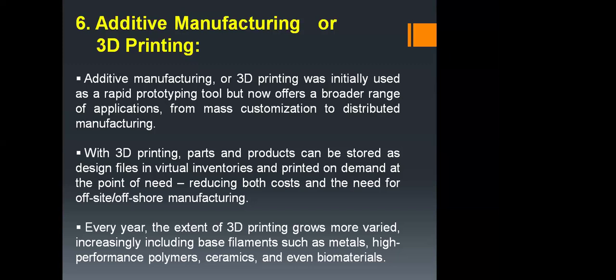One thing to mention here: additive manufacturing was primarily invented or designed for polymeric materials because they are well suited for 3D printing technology. But nowadays, with the advancement of time and technology, we are going for 3D printing of metals also, even ceramic materials, composite materials, and biomaterials. In the field of biomedical applications, the additively manufactured parts are very much suitable, and the demands are day by day increasing.